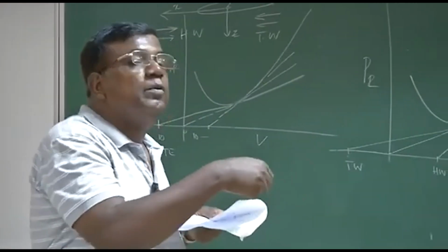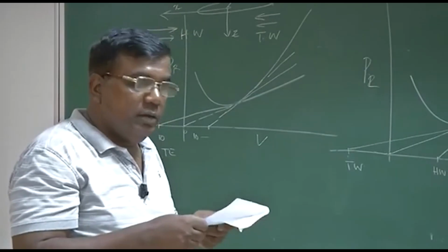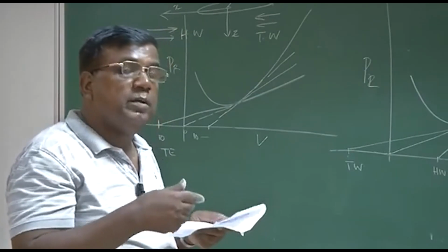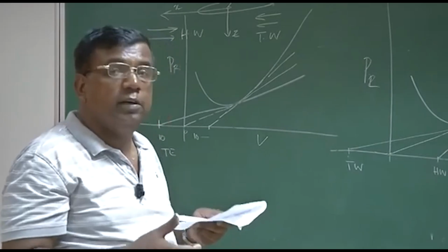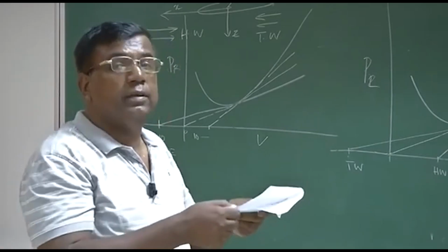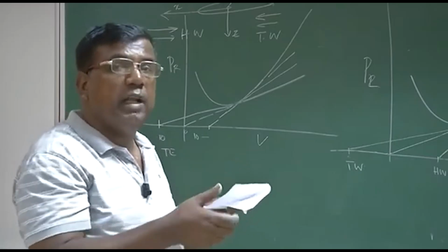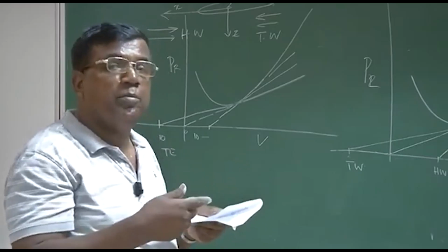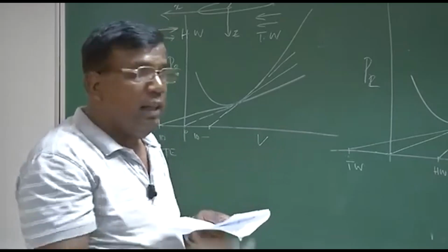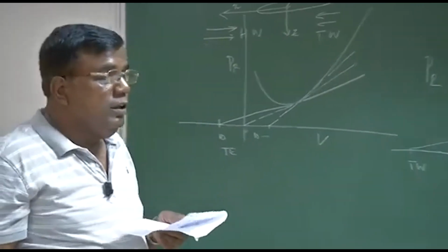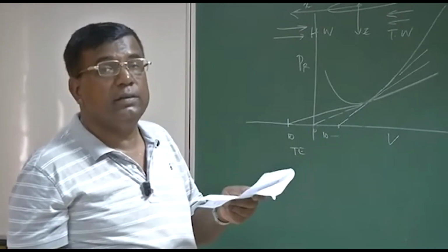The air relative speed will reduce, isn't it? As it reduces, because we are talking about air relative speed with respect to the atmosphere. That is reducing, so lift will reduce, so you have to increase the ground speed. Okay? To ensure that you have got same air relative speed to balance the lift. In the process, what will happen? You will reach Lucknow faster. Right? In contrast, if you see, when I am going from Kanpur to Lucknow, there is a headwind.